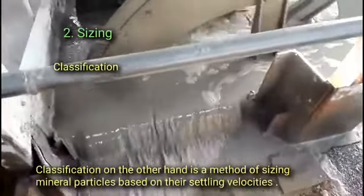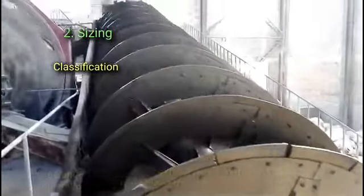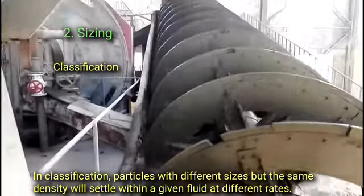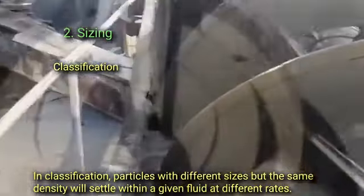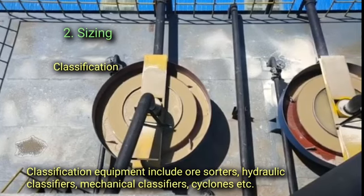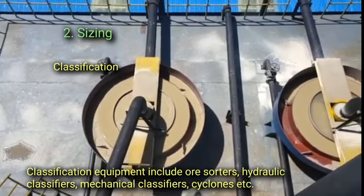Classification, on the other hand, is a method of sizing mineral particles based on their settling velocities. In classification, particles with different sizes but the same density will settle within a given fluid at different rates. Classification equipment includes ore sorters, hydraulic classifiers, mechanical classifiers, cyclones, etc.